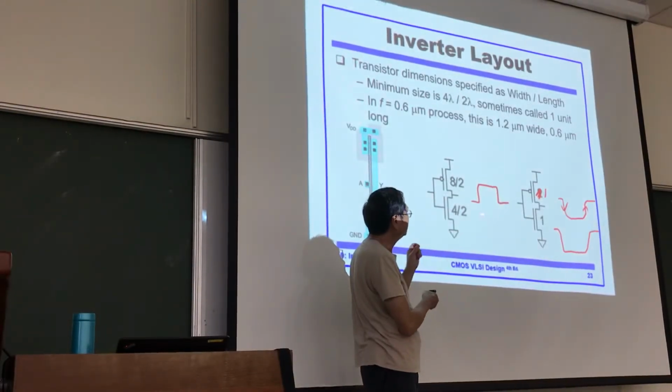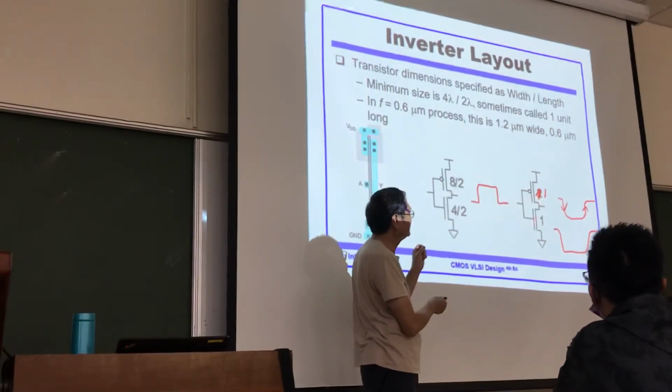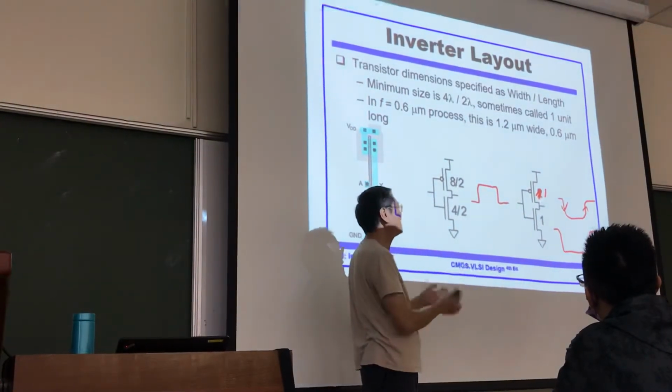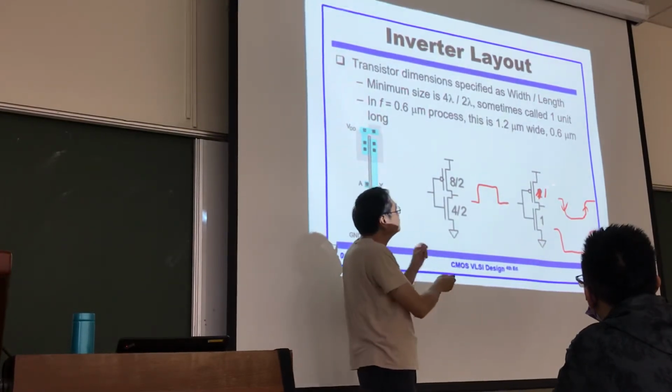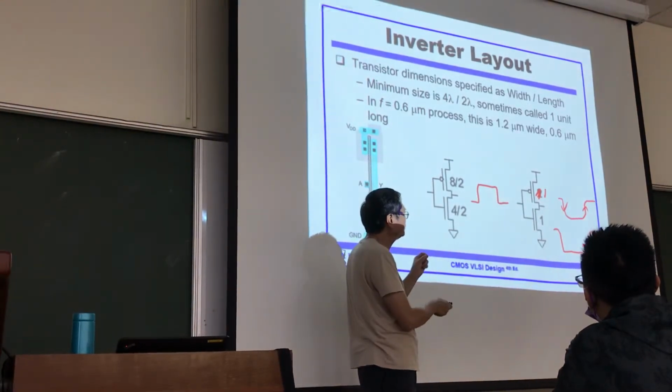When input from low to high, signal 1 is going to turn on NMOS transistor, right? And because NMOS transistor is faster, you are getting to low voltage level faster, using less time to reach the final value. On the other hand, PMOS is slower, so it's going to be slow for you to switch on from low to high. Okay?